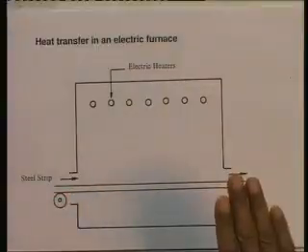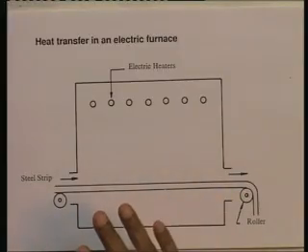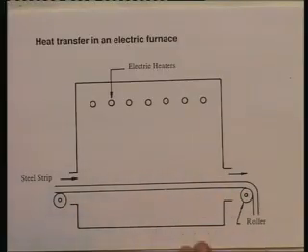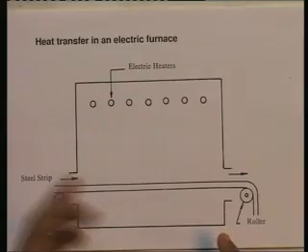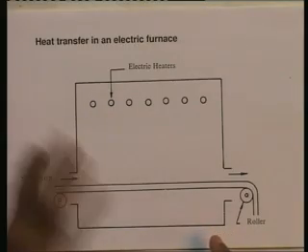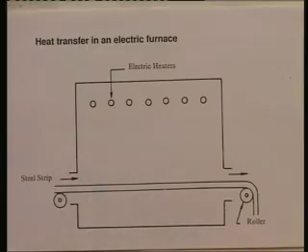The heat treatment process here consists in heating that steel strip up to a temperature which is specified for steel, heating it just above that specified temperature and then allowing the steel strip to cool down slowly. So, the job of this furnace is to heat the steel strip up to a temperature required for that heat treatment process to occur, usually around 600, 700 centigrade, of that order.